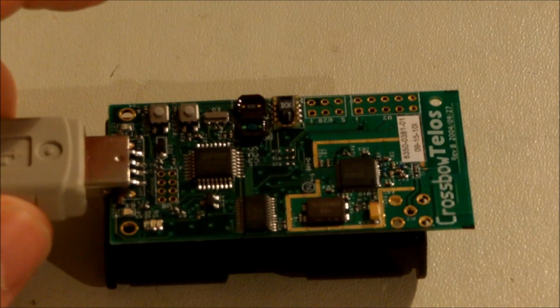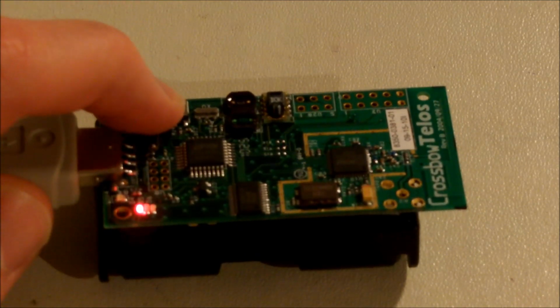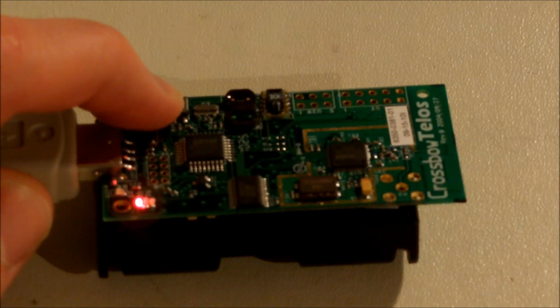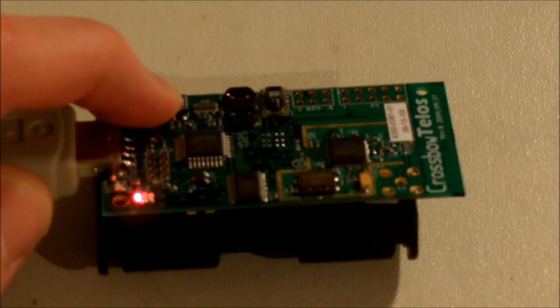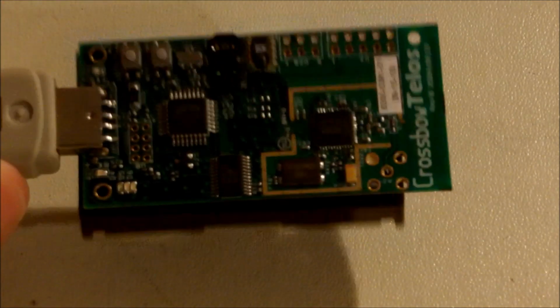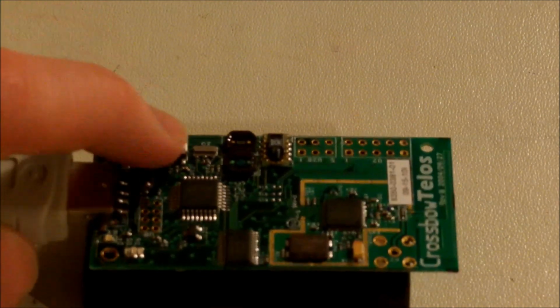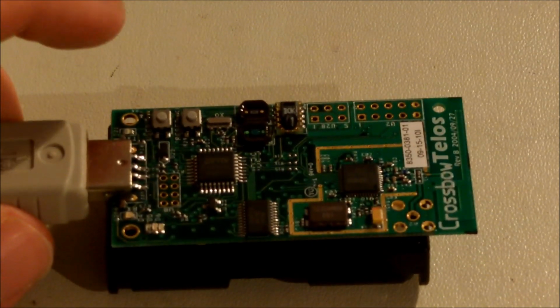So for example, you can implement some timers in your code that, for example, if the switch is being pressed for more than 20 seconds, then you do something. If it's being pressed for more than 30 seconds, you do something else. If it's pressed for 1 hour, you do something else. This is particularly good for example, for you want to keep track of a door being open or closed. So it's very easy to do by adding some timers to your code.